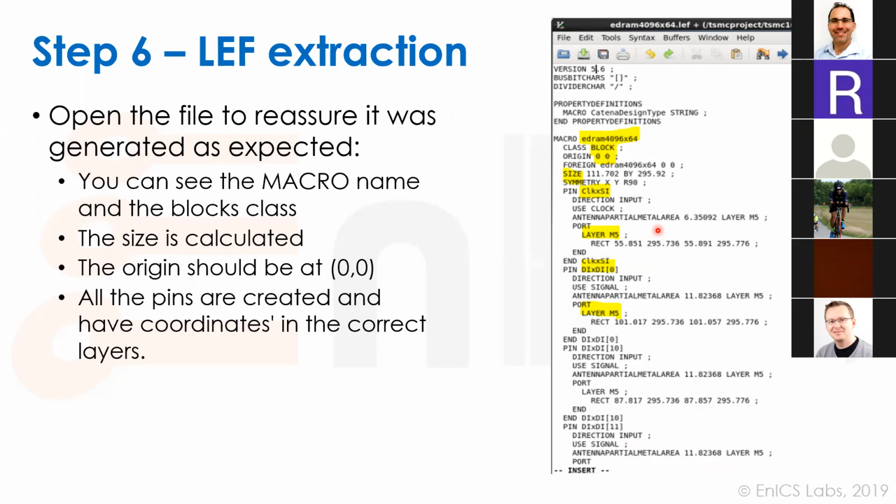We missed some DRC checks, or we didn't check any antenna DRC, because we were using an incremental antenna DRC file instead of the main DRC file.